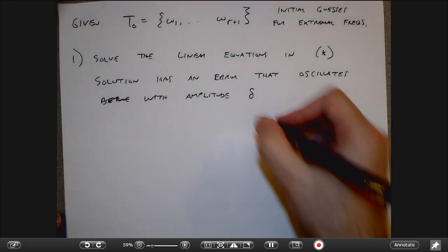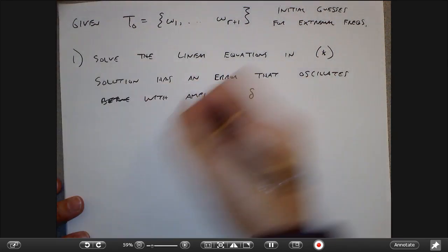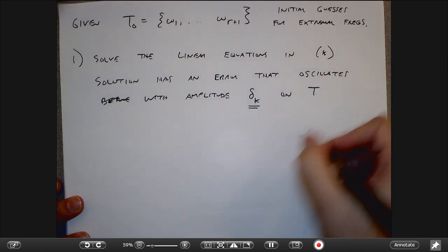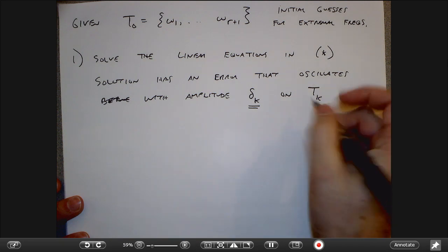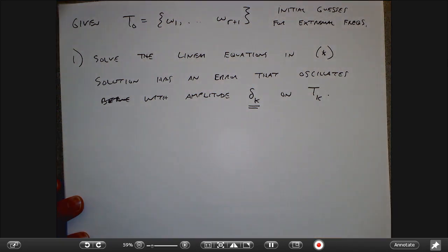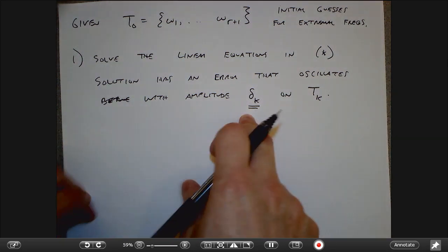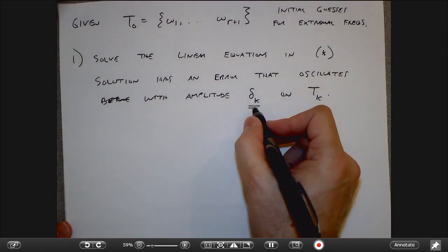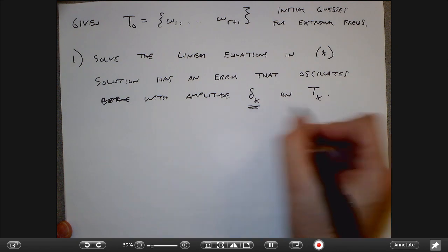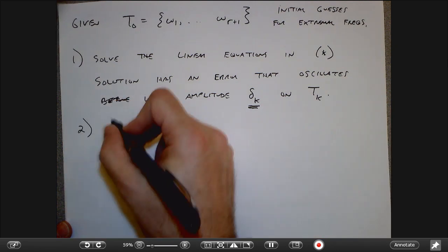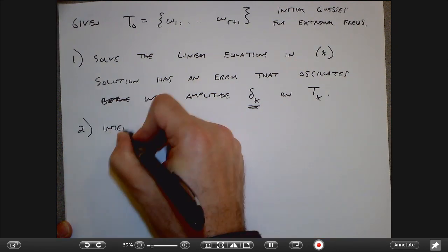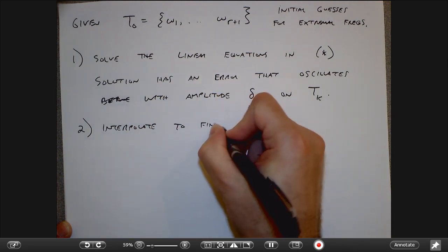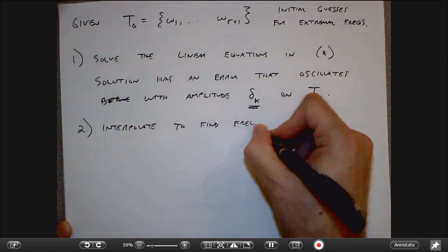This is going to be an iterative thing, so I have an error at a given point delta, and I have a set of points t_k. That I can do for sure. So I find out what my extremal error was. And now I can interpolate that frequency response to find what happened at all the rest of the frequencies.